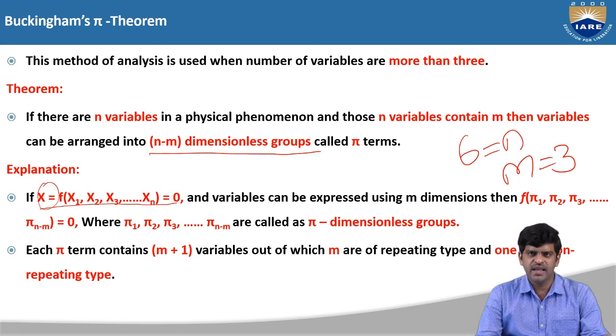So according to the Buckingham pi theorem, in a brief overview, if there are n variables, either dependent or independent, and those can be expressed in terms of the M, L, T quantities, that is, 3 quantities, these can be arranged into n minus m dimensionless groups, also called pi terms.